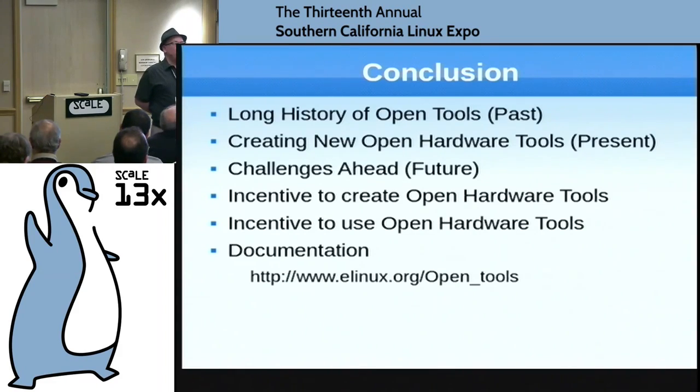The advantage to using Eagle with SparkFun libraries is you can go to SparkFun and say, I want this LED, I'm going to order 10 of them, and at the bottom of the page is the library for that part. That is a big advantage, especially for somebody that's new to hardware development and may not know how to create their own footprint and symbol. So if you want to create a small board for the first time, you have the libraries to get started and get your feet wet. But I agree, there are tons of libraries, they just tend to not be connected. Say, here's the library part, and here's where you order this part and get it all together at one time.